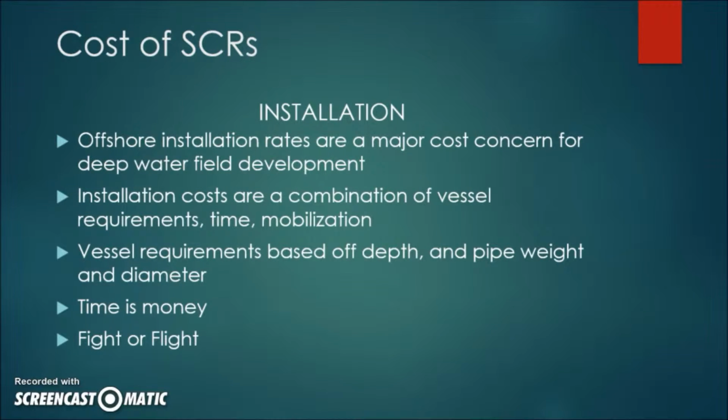The second is the installation. Offshore installation rates are a major cost concern for deep water field development. Installation costs are a combination of vessel requirements, time, and mobilization. Vessel requirements are based on depth and pipe weight and diameter. And every day the vessel is out there, it costs you money. During a catastrophe, the vessel will either fight or flight, which will cost money. That means they'll either stay and tough it out, or they'll leave when something bad happens.